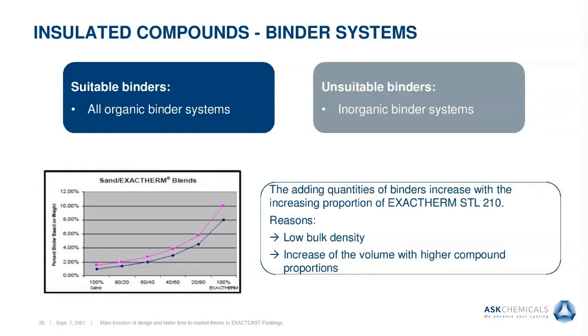In smaller castings or with short solidification times, it might be possible to use an inorganic binding system, but an organic system is recommended here.